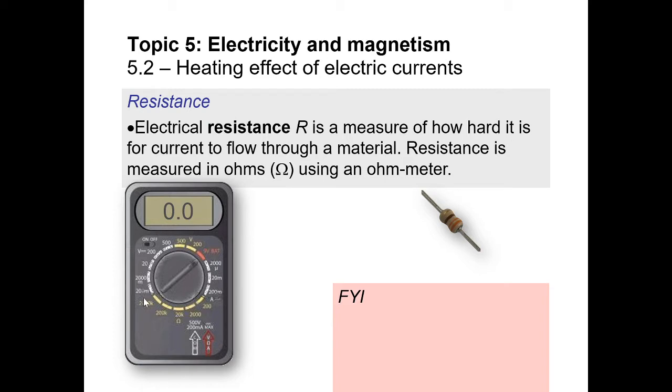So this is a nice digital device that can measure all 3 of those quantities depending on where you set the dial. On this one, I've got voltage measurements on the top left, current measurements on the top right, and resistance on the bottom. But you'll notice that there are different settings: 200, 2000, 20K, 200K, 2000K. All that means is whatever range your resistance is expected to be, you would put the dial on that spot. So for instance, if the resistance is expected to be in the 300s, you would put it on this first dial right here. If the resistance is expected to be in the thousands, you would put it on this next dial. In the tens of thousands, the next dial, etc.